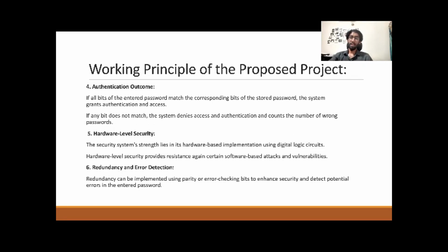Authentication outcome. If all the bits of the entered password match the corresponding bits of the stored password, the system authenticates and grants access. If any bit does not match, the system denies access and authentication, and counts the number of wrong passwords. Hardware-level security. The security strength lies in the hardware-based implementation using digital logic circuits. Hardware-level security provides resistance against certain software-based attacks and vulnerabilities.